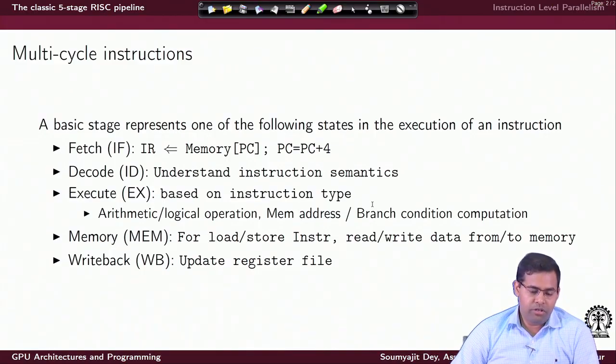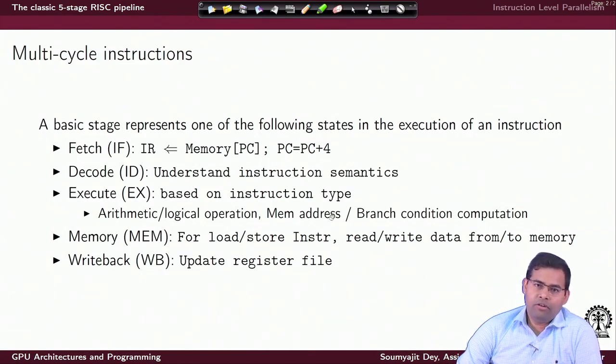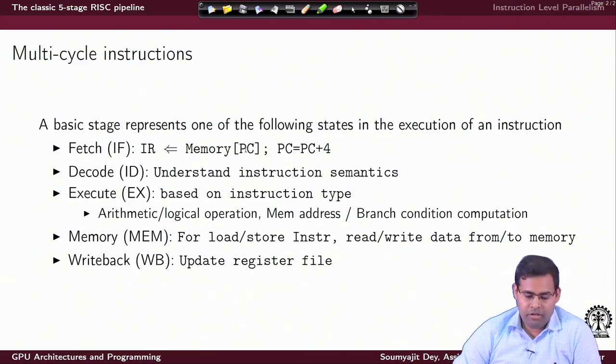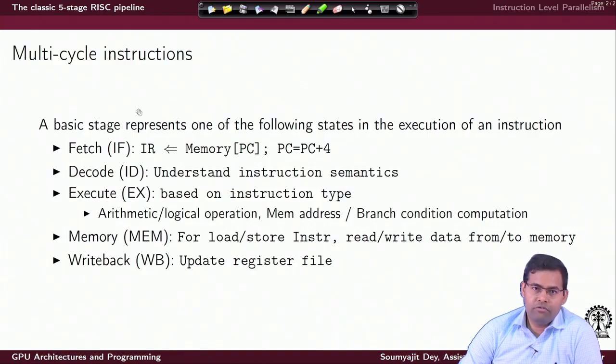The first stage is what we call the instruction fetch stage, where we check the content in the memory for a location that is loaded into the program counter, marked here by this PC, and load the content into a specific register called IR, the instruction register.